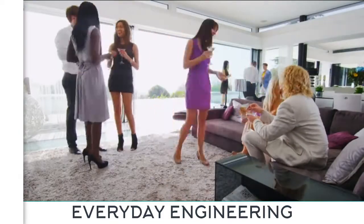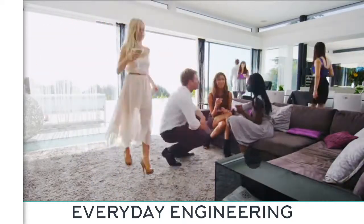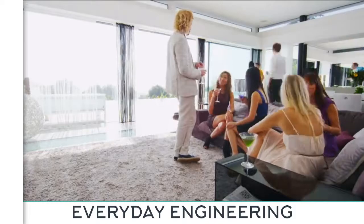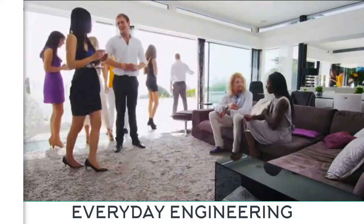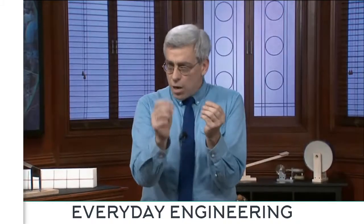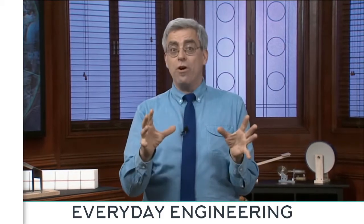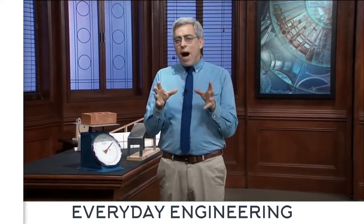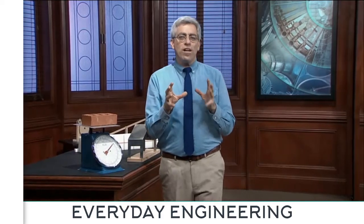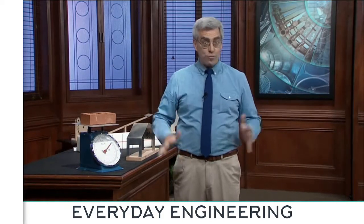Live load consists of the weight of people and all of their movable stuff, like furniture, books, and housewares. Live loads are highly variable in both magnitude and position, and they can change dramatically over time. Given this inherent unpredictability, we need to rely heavily on the institutionalized wisdom of the building code to help us estimate these loads. For example, according to the International Residential Code, my living room floor should be designed to support a live load of 40 pounds per square foot applied to the entire floor surface.